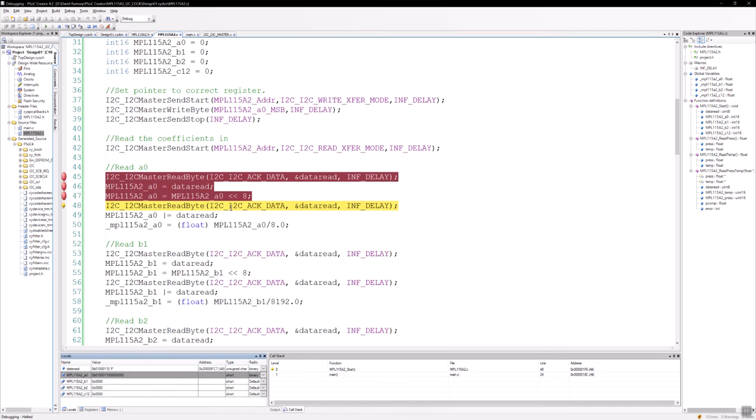All right, now we're going to read the least significant byte of data in. Okay, so we're going to step over that command. And now this is the least significant byte of data. And then we're going to step over that. And suddenly we can see that we've got that binary number stored there. Now, of course, we could store it as a hex number, or if you wanted to, you could put it as a decimal number. But I like to just look at it binary for now, because that way we can see it between here.